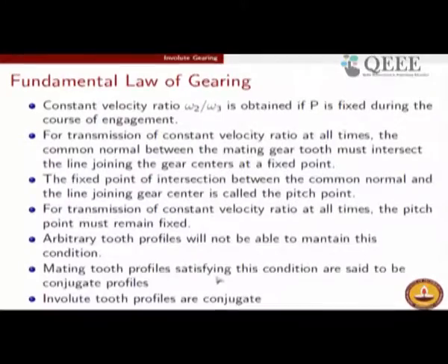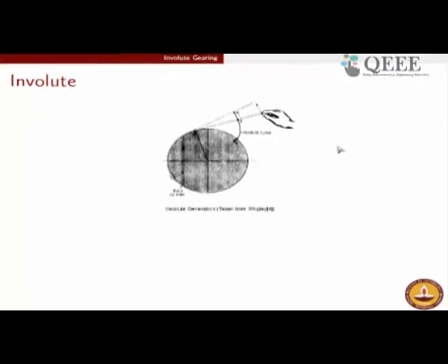Now we will get back to the theory once more. We will return to this model to explain a few other things about gear geometry. Okay, so coming to what is an involute. The definition of an involute is pretty simple. If you take a taut string and unwind that taut string, any point on that taut string will generate an involute. So the locus of any point on a taut string as the string is unwound from this circle is going to generate the involute of a circle.